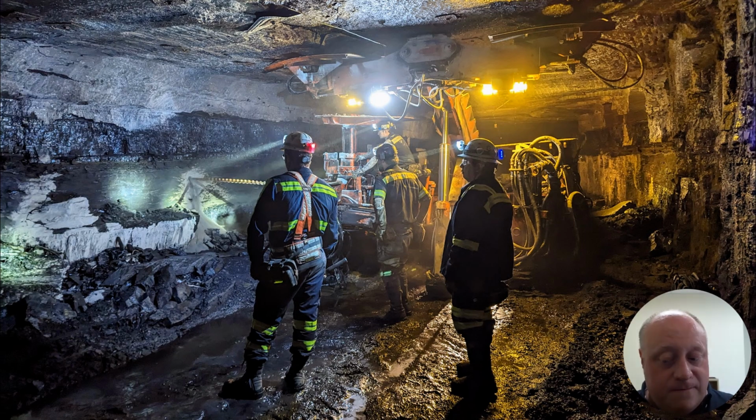So a lot of times their cutoff for mining is this parting thickness, and there are places where it's 4 feet thick. What I was trying to do was determine how much that rock parting impacted the strength of the pillars on this section.